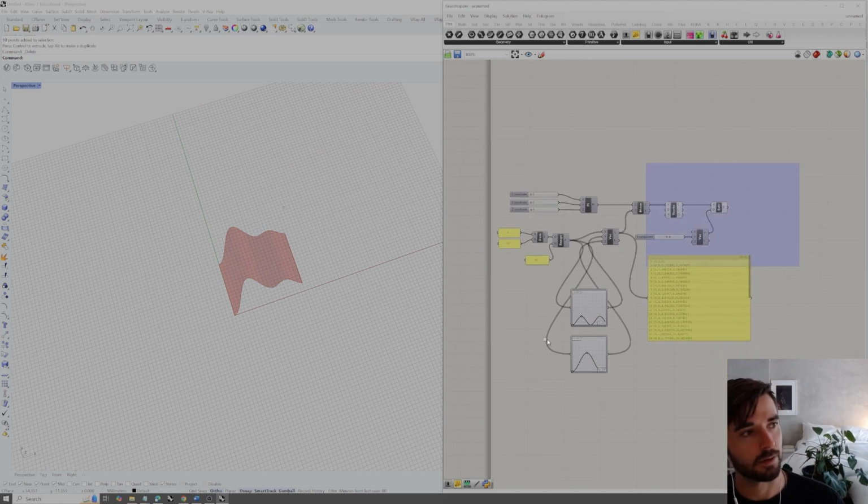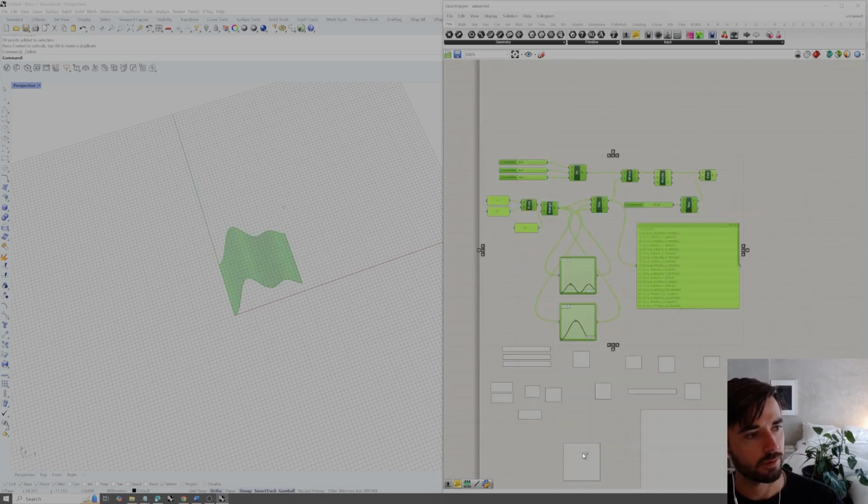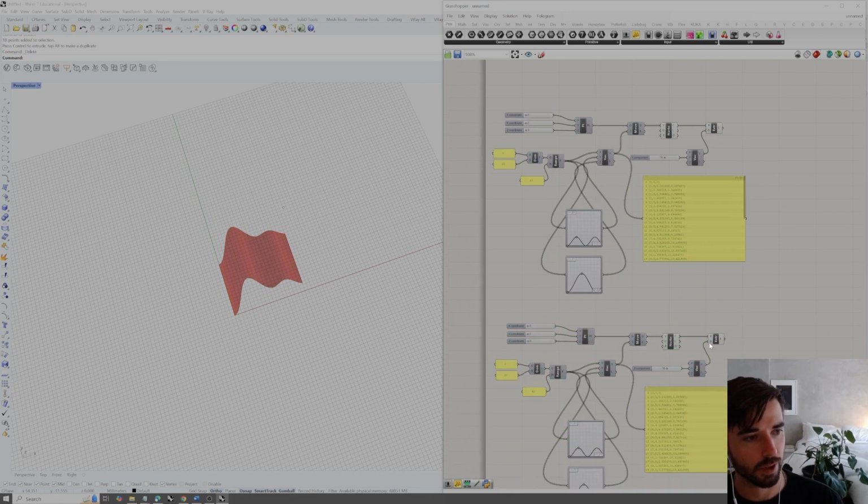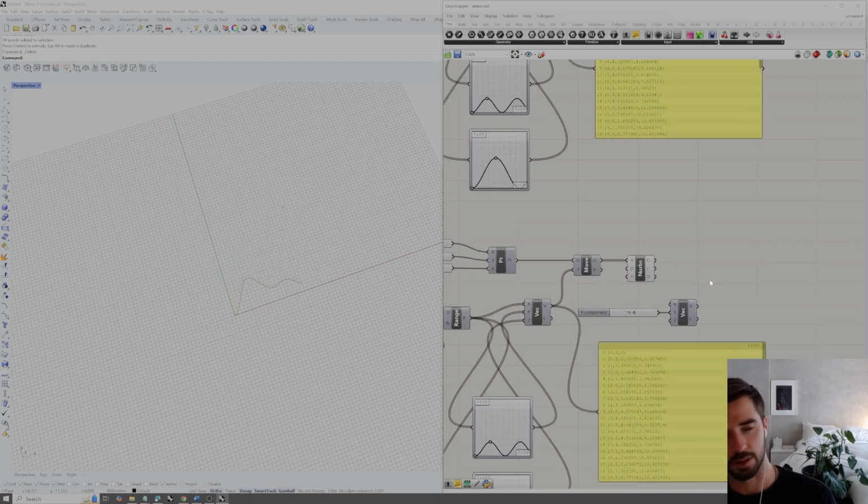If we wanted, instead of just extruding, to have two different curves controlling that surface geometry, we would want to use lofting. So I'm disabling the preview there, deleting this extrusion, and then I'm going to double click and type loft. So Loft takes an input set of section curves and then options, which right now we can just leave default, and then it will give us resulting lofted surfaces. So all this means is that we want multiple curves being fed into this curve input.